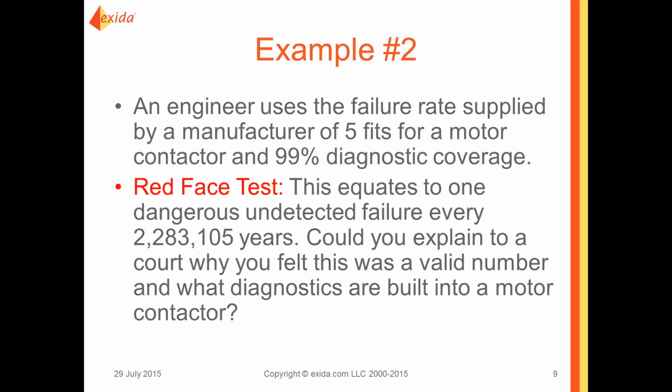So could you explain to a court why you felt, one, that this was a valid failure rate, and two, what diagnostics are built into a motor contactor? And as I'm sure most people on the webinar realize, a motor contactor is contacts that are made or broken by energizing a coil that pulls back a movable piece. The only way to test that is with a proof test.